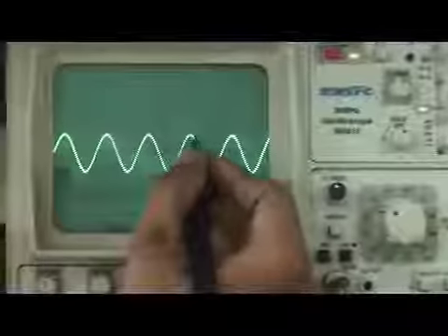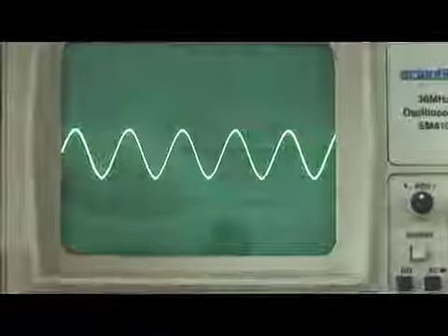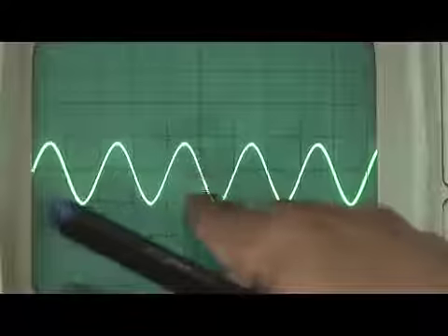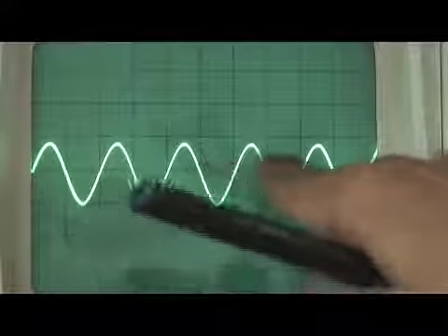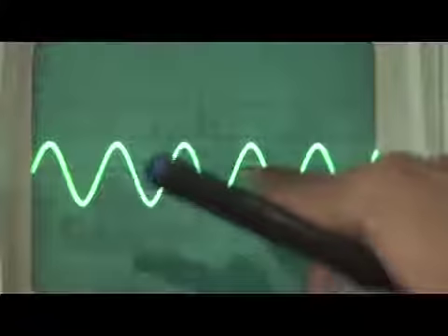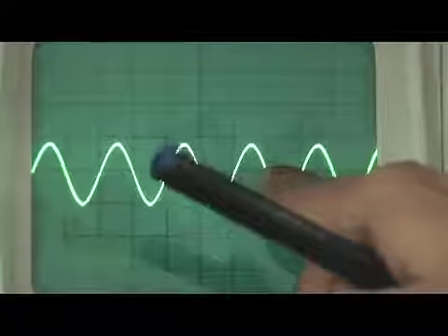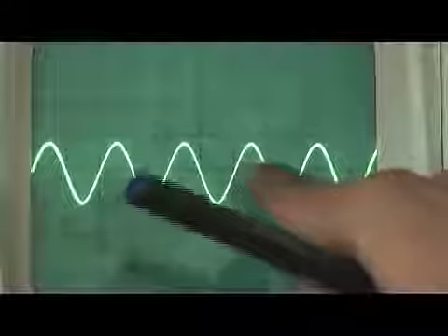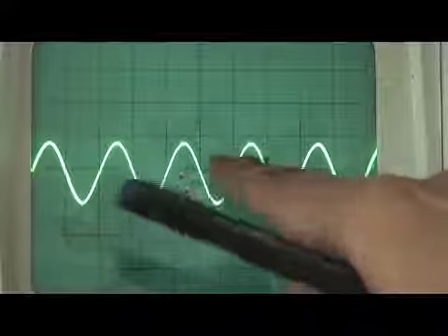Next we move to how to calculate the frequency. Again make it ground, bring it to the center of the line, release the ground, and set this y-axis in such a way that you can easily count one cycle. If I set it here, from this point to here is one complete cycle. How many blocks does it require to complete it? It requires 1, almost 2, or let us take it as 2. So it is 1 block, 2 blocks. To complete one cycle it requires 2 blocks.